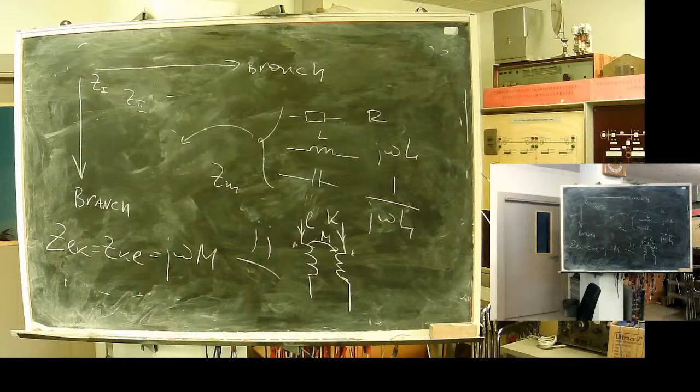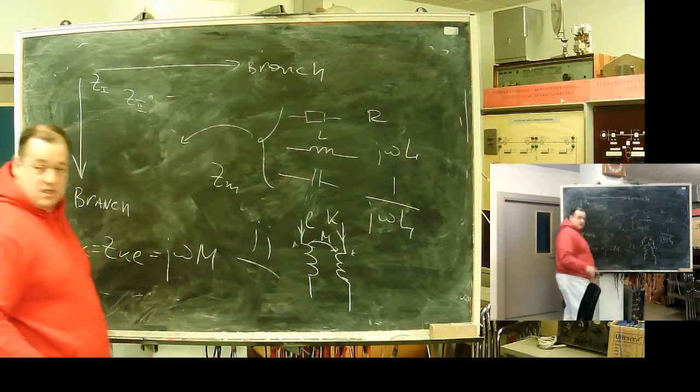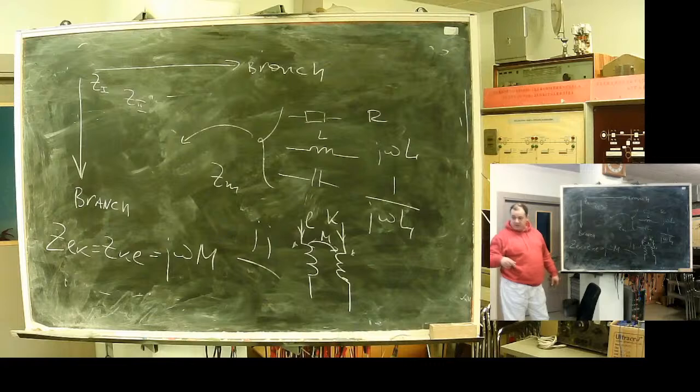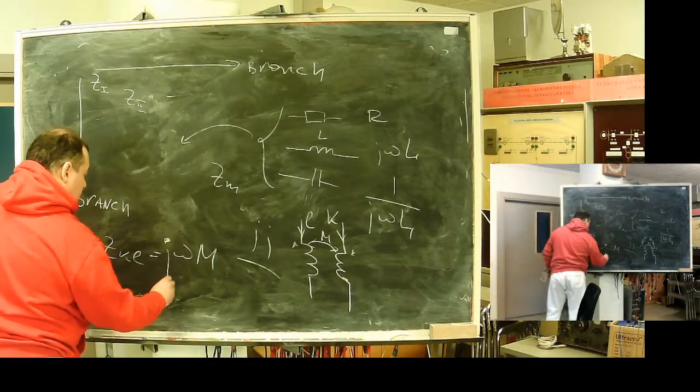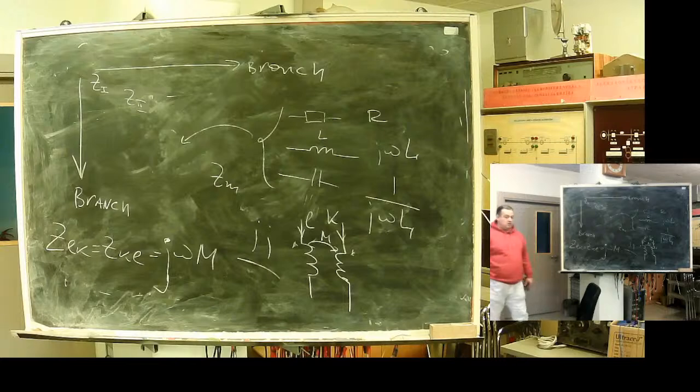In case we have transformers, something like this, and we want to represent mutual inductance, we write them in the resistance matrix as non-diagonal elements. They will be symmetric. So if between branch L and K there is a mutual coupling, they are connected with common magnetic flux. We need to write it symmetrically as j omega times the mutual inductance.